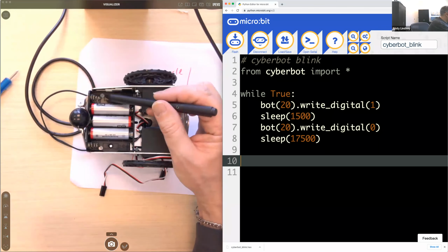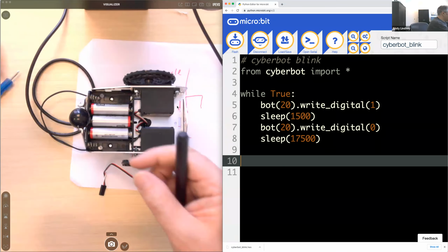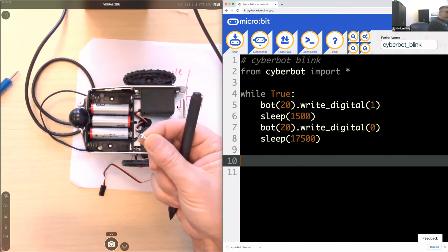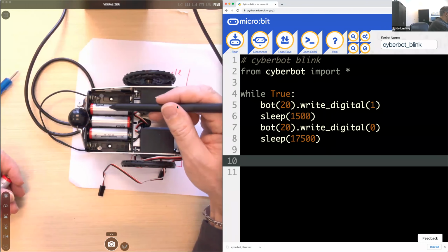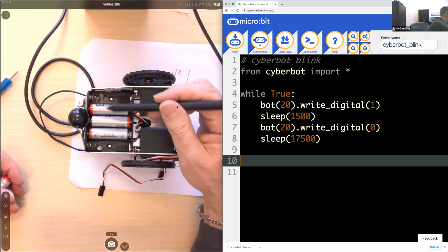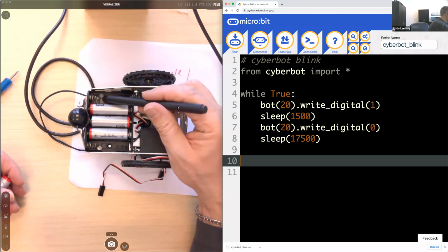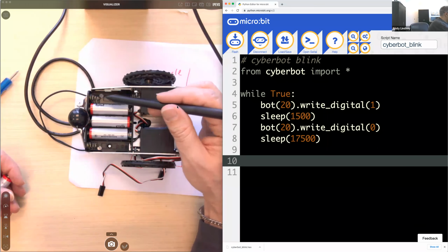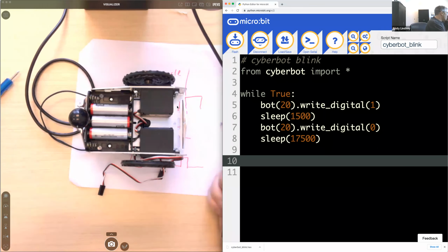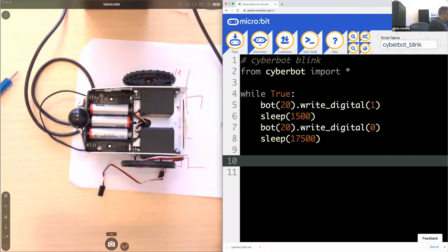It's really important because this kind of metal screw can actually nick this plastic covering on the battery and then short the battery. That's underneath this plastic cover. It's got voltage on it, and if you short that voltage to this chassis through the battery pack, it drains the battery very quickly. The battery pack gets hot. It's not something you want.